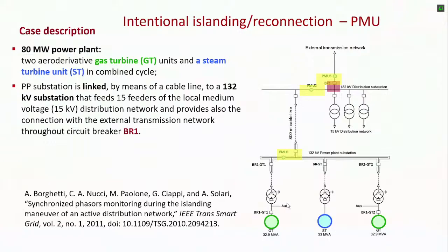It is a little bit difficult to find PMUs for distribution networks, because for this kind of study we need some specific requirements that are in general not covered by the typical PMUs installed in the transmission network. Since we are involved, we have developed the PMUs in our laboratory, so they were in-house PMUs and not directly bought from the utility.